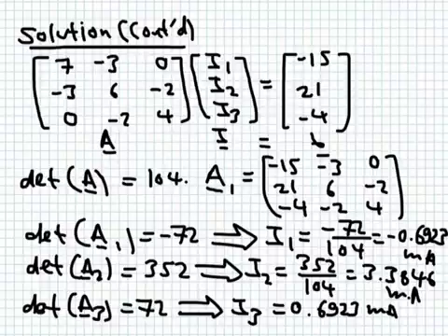Then we know the currents everywhere in the circuit. Why? Because every branch is either owned by just one loop or it is shared between two loops. If it is shared between two loops, then we subtract their two currents. If it is only owned by one loop, then the current of the loop is the one flowing in that branch.